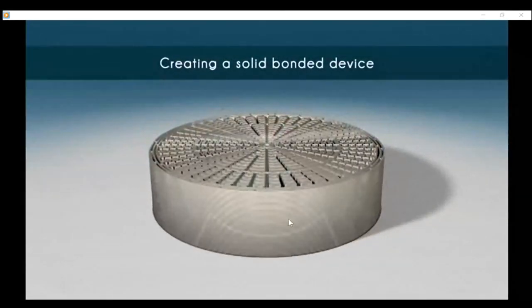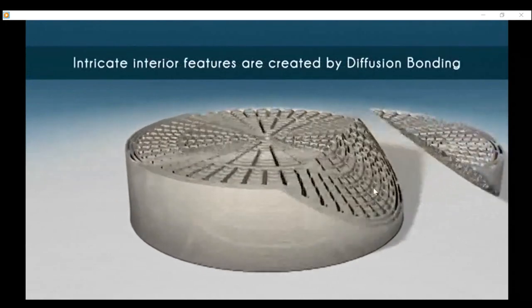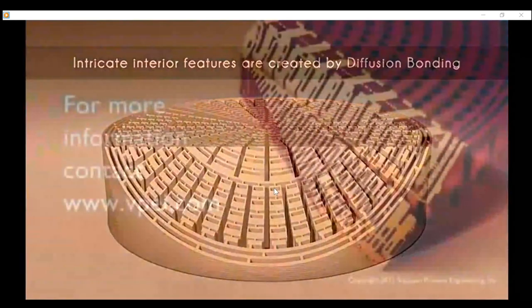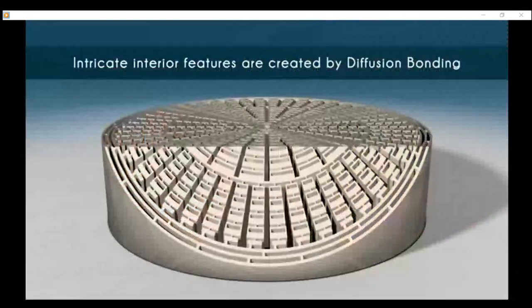Then later, you see it become one part. All these parts become one part. If you cut here, you see the material welded. It takes time for this to happen. So what are they doing? They heat this material because it takes time for the weld to happen. Why heat the material? To encourage atoms to quickly move up and down. Then the bond will be created in a faster way, right?